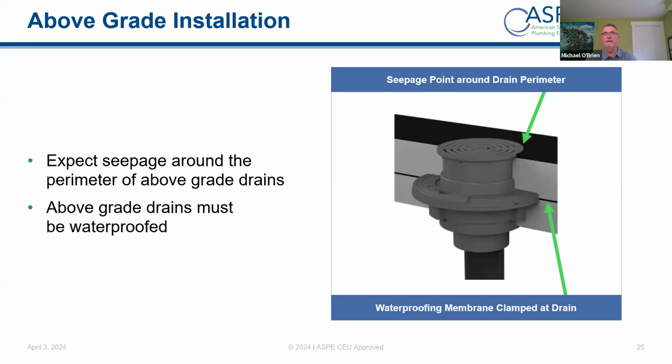There are a couple of ways that you can do that. One is you add on, at the outlet, you would tie into the membrane with this type of clamp added to an outlet. Or if you're lucky to deal with a fabricated trench drain company, like myself, we have developed a system where we can handle that all the way around the trench drain.